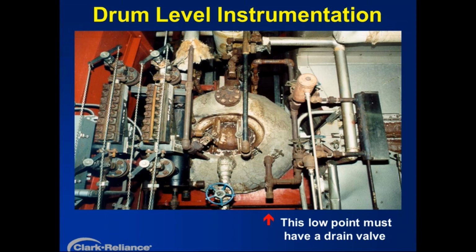When we go off to the right side, we are seeing some missing insulation on the piping, and we see a condensate pot and a lower connection with the two silver-colored tubes coming down. Those are the sensing lines for the DP transmitter. Off to the right is a conductivity probe device. The problem that happened here is that U-shaped trap in the piping above the red arrow one day began to clog with sediment in this particular application, and both of those level transmitters were reading higher than the actual level in the drum because that trap became restricted.